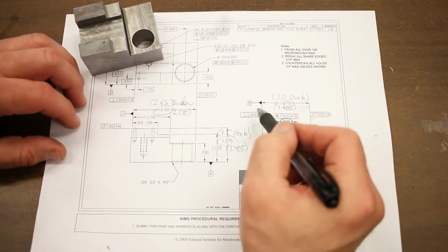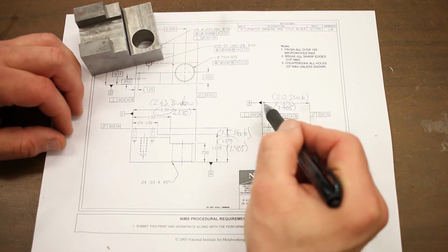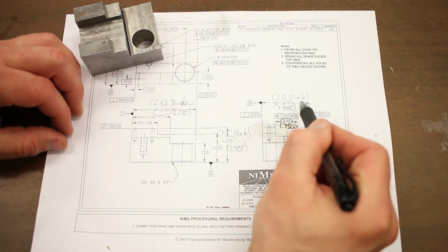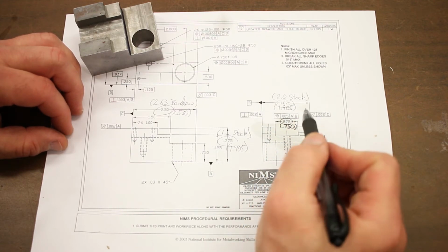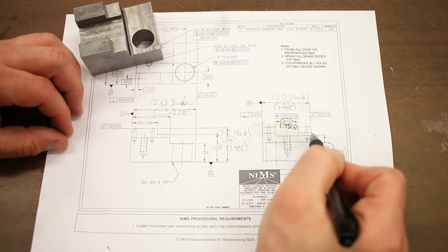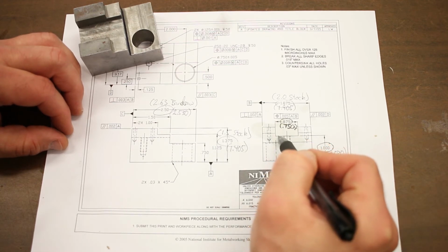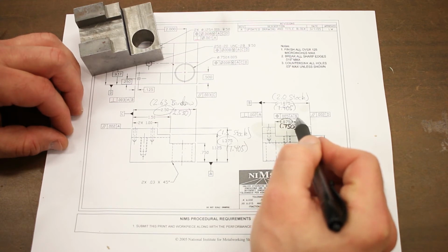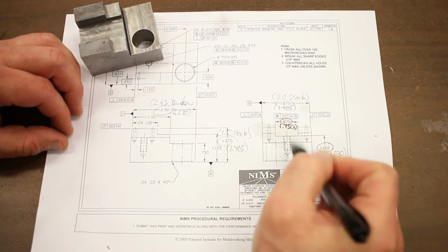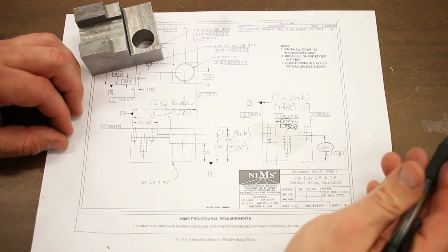So you might think to yourself, well, then B and D are redundant. But no, datum B, because of its position, means that it is a center plane constructed from this surface and this surface. So then what does it mean for the slot to be positioned within 5 thousandths relative to datums A and B, the bottom of the part and the center plane of the part between datum feature D and its opposite surface?